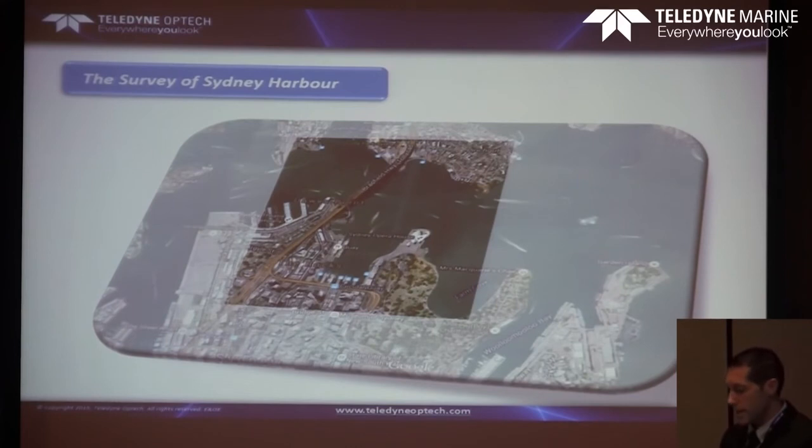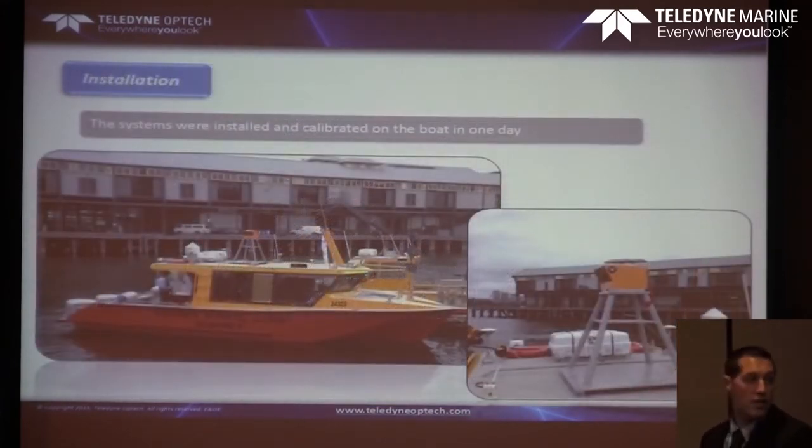In order to do that, they had their own installation. This is the boat, as I said before. Some clients prefer to use their own platform, and in this case they built this stand. It was actually very good. The way we usually do it, we send the drawing of our scanner, and whatever they build is usually fine. One important thing is to have the scanner as high as possible on the boat, because you have a better view of the object that you want to scan. This is obvious, especially if you want to scan a shoreline. You need to be high so you have more data.